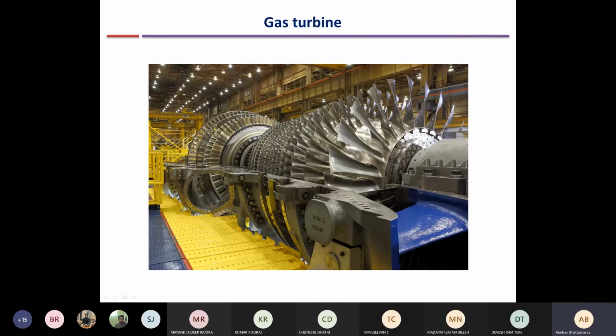What happens is that you cannot dramatically increase it. There is a huge amount of work input required for increasing the pressure in the compressor, and each stage cannot handle more than a 1.4 or 1.5 pressure ratio. If I want to increase the pressure ratio to say 50:1, the number of stages required will become too high. In real life, each stage will have its own frictional and associated losses, and the weight of the engine will also increase dramatically if you have a very large number of stages. So from an engineering point of view, it is better to have a limited number of stages. Still, the number of stages can become quite high, 12, 15 like this. But the main reason is that a single stage cannot handle more than a certain pressure ratio, 1.5:1 or something like that.